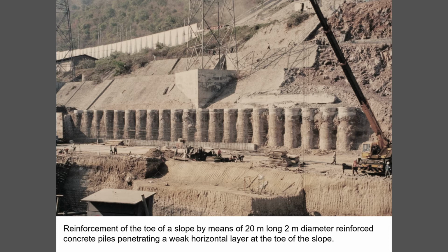This is a rock slope behind a large powerhouse, the powerhouse in front of us here, and behind the powerhouse are a number of columns that carry the power lines. And so you see there in the middle of the photograph the foundation of one of the columns, and obviously you need to protect the slope against failure in order to ensure the stability of that column, which would destroy the power line, or run out onto the powerhouse below. And so the solution adopted here,